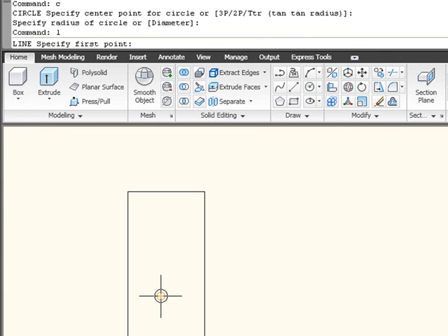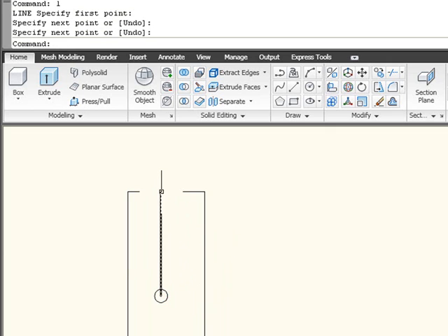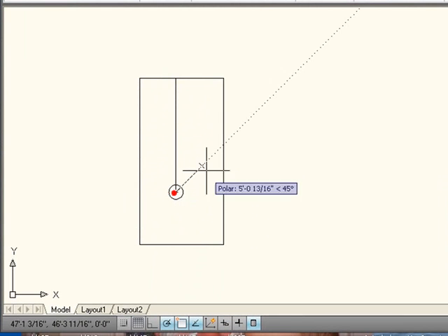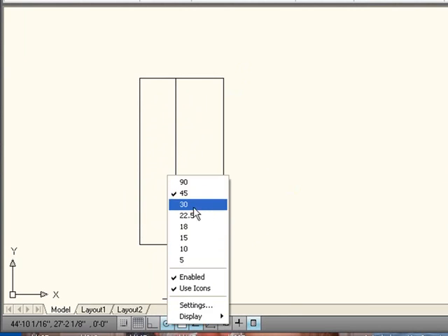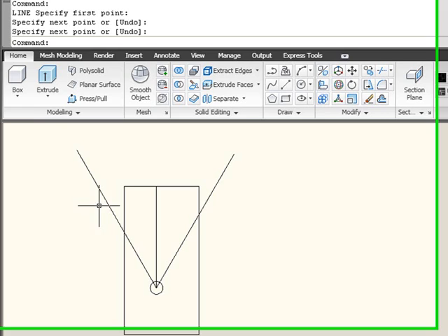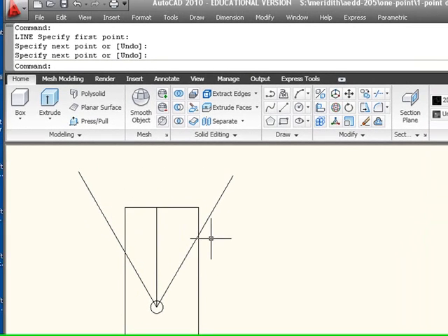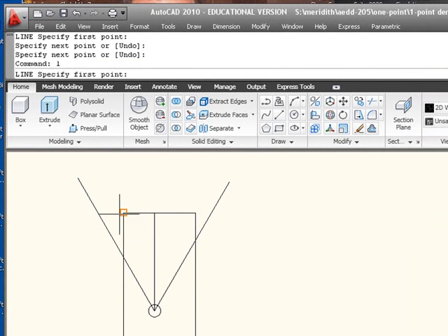So this would be the center of our head, the center point here. This is where the vanishing point would be located based on the position in the room. If we draw a line from the center of the head and use an angle of 30 degrees on both sides, that is what's called our cone of vision. We have a 60-degree angle cone of vision. As long as the two corners of your room are within that angle, then your one-point perspective will come out pretty well. And then this back wall right here, we're going to imagine is our picture plane.